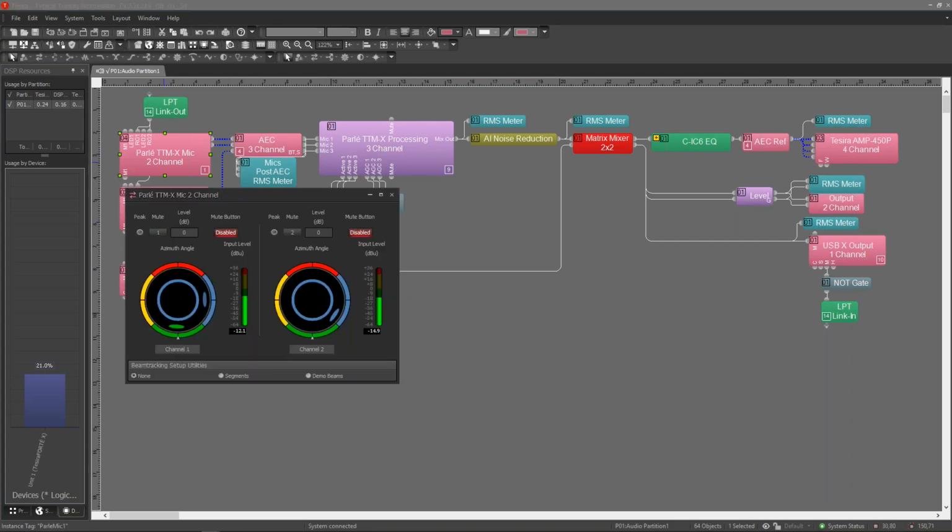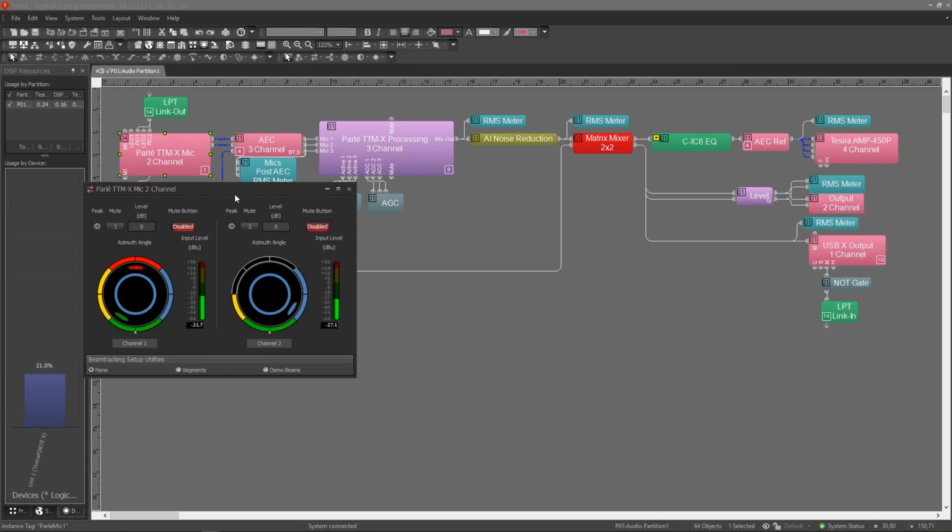And then move over to the left-hand side and tailor your microphone coverage first. I'm using Parlay as an example, but it's true for any microphone. So, the directionality of the mic, it could be in the design stage, what polar patterns are we using, or if you're using another beam steering type of microphone, you want to tailor the coverage first. If I'm speaking over here, and actually this microphone may be up against the wall, let's tailor the coverage and turn off the bits that we don't want to actually use anyway. And I'd suggest doing that at the outset so that you're only covering the areas you want to.